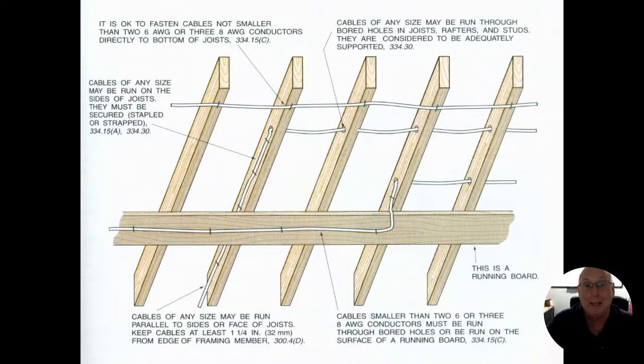But as far as non-metallic cable, just about everything that you're going to use out there or outside the city of Chicago is pretty much going to be NMC. In fact, just to be really clear, other than New York, Chicago, and Los Angeles, everywhere else in the United States of America, and I'm talking about the city itself plus the surrounding burbs and the locale around the city, they all use non-metallic cable for residential buildings. All right, everything for commercial buildings has to be in conduit, but residential buildings, non-metallic cable is just fine.